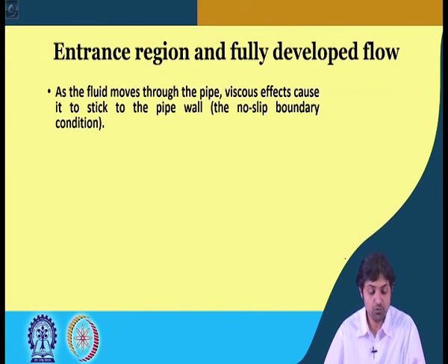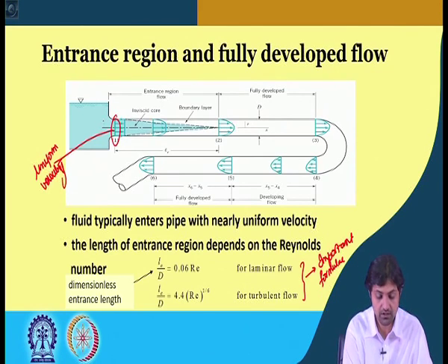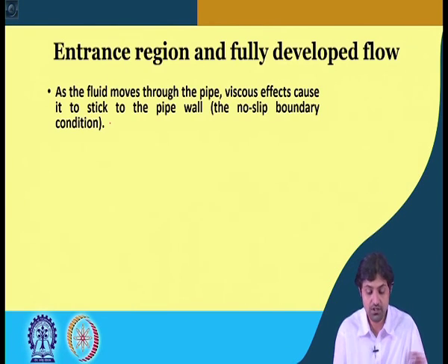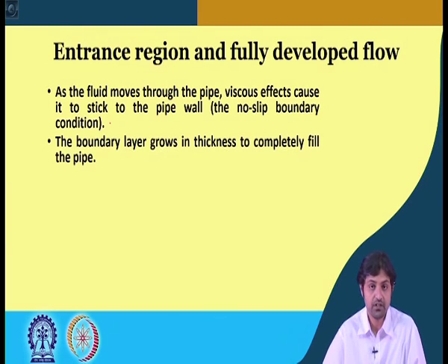Now as the fluid moves through the pipe, viscous effects cause it to stick to the pipe wall because of the no slip boundary condition. As I told you, as it starts moving, because of the no slip boundary condition, the viscous effect will cause it to stick to the pipe wall, and the boundary layer will grow in thickness to completely fill the pipe.